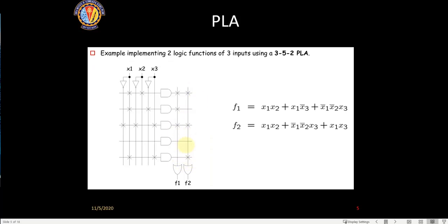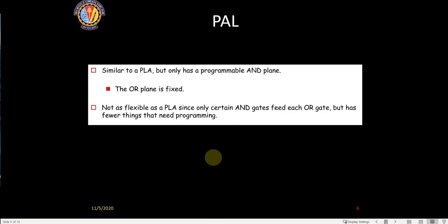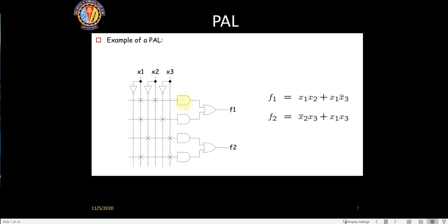At each of these links there will be a floating gate MOS transistor switch, which can be programmed. In a PLA, for each of these junctions, 1, 2, 3, 4, 5, 6, 7, 8, 9, 10, more MOS transistors will be required, which can be programmed for these connections. In a PAL, they are already hardwired, so there is no way you can program that. So it will become compact because those MOS transistors are not there.